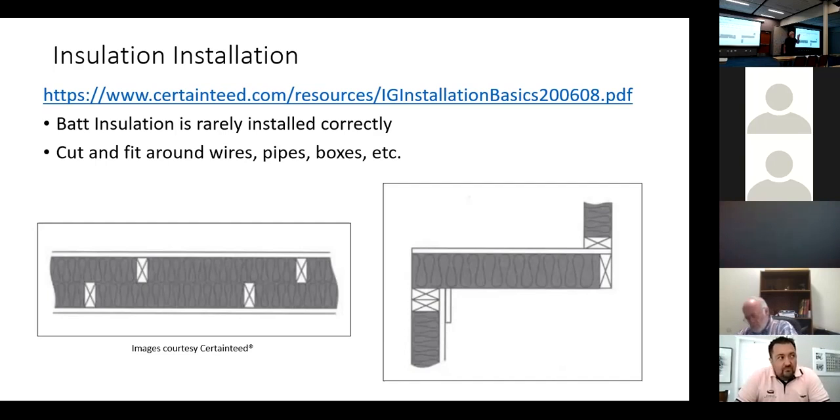And how do you six-side a rim joist? What about foam insulation when you've got a 2x6 and you're only going 3 inches or 4 inches of foam, and you still have 1.5 inches? Well, foam insulation, we don't have the air moving through it.